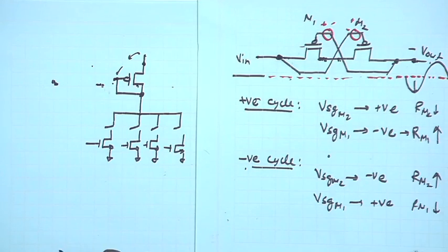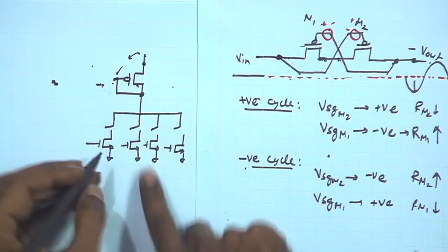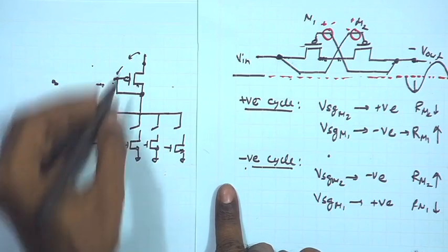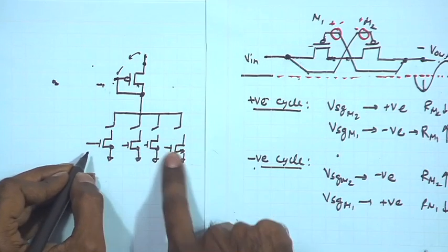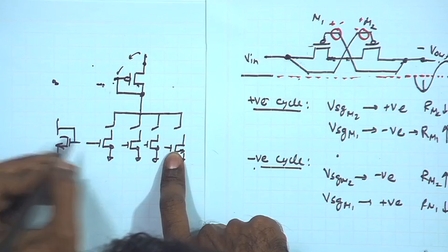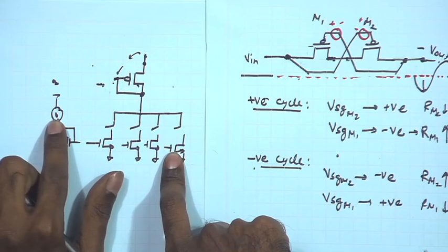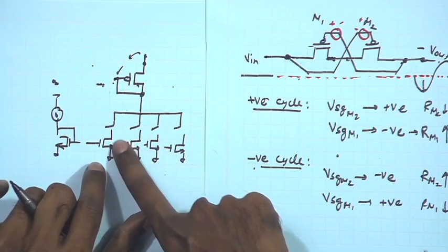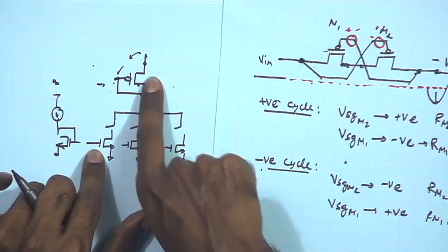So, let us look at how by tuning some of these switches drawn over here we can tune the VSG. As we know, if we have these transistors operating in sub-threshold region, suppose these transistors are implementing some kind of current source mirroring a very small current. So, we can ensure mirroring of very small current of the order of say sub nanoamperes, such that the total current even summed up with all these 4 transistors is very small flowing through this PMOS.